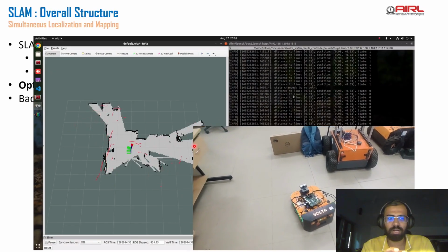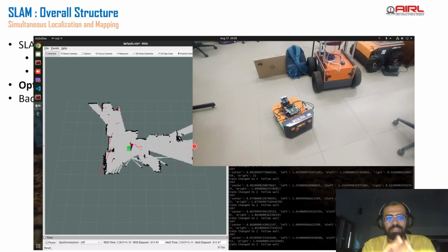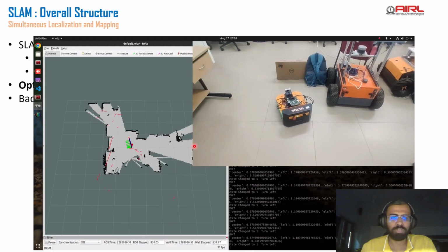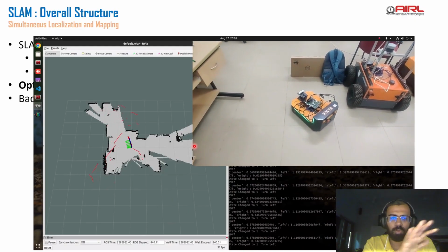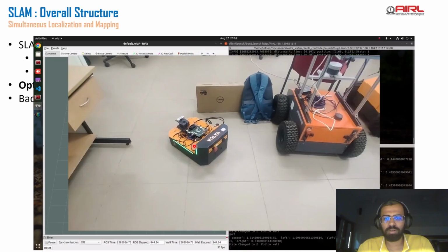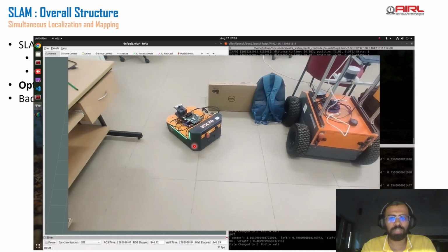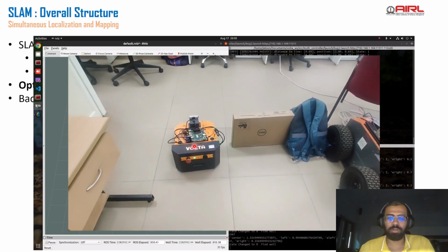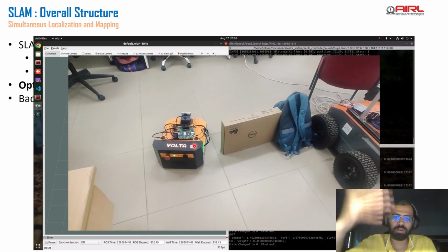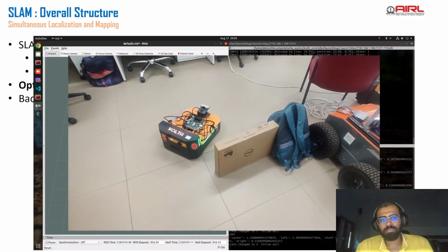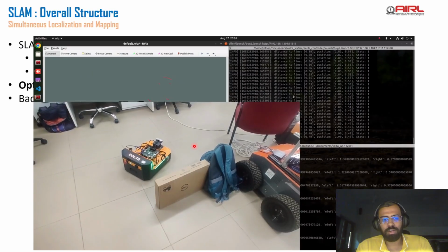The laser scan is direct, whatever reading you get, it's just that. So the poses are not correct, and it's not properly going to overlap with your map here in this picture. And you see there were two obstacles and it's nicely avoiding those two obstacles and going around them. So the end point was given on the other side of the obstacles, right? Let it do that.